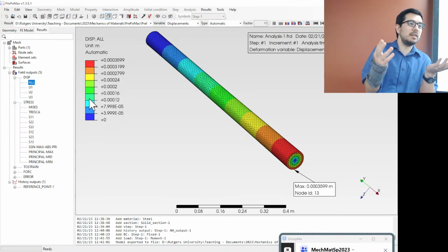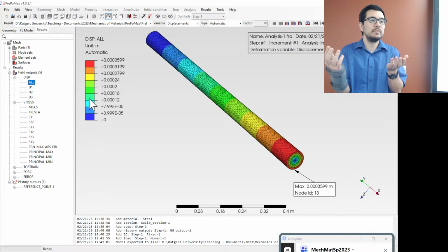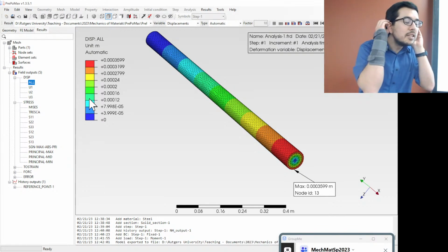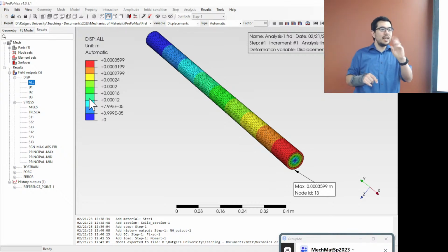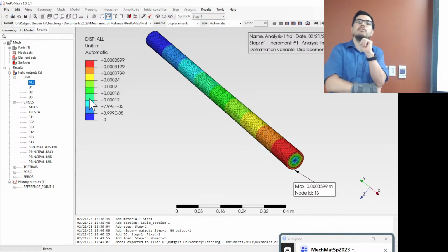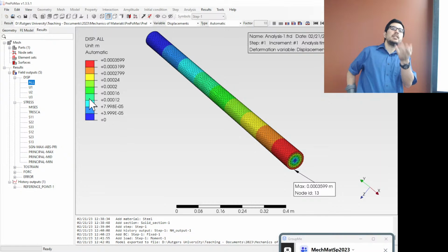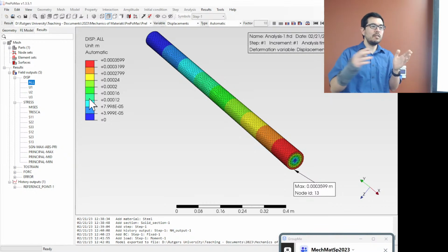And so what do you suggest that we do? What is our test for that? Yes. Minimize angle of twist. Say that again? Minimize angle of twist. Okay. You could minimize angle of twist. And yes, there's going to be some connection, because if there's a huge angle of twist, that could potentially have a large shear strain associated with it, which could have a large shear stress, right?